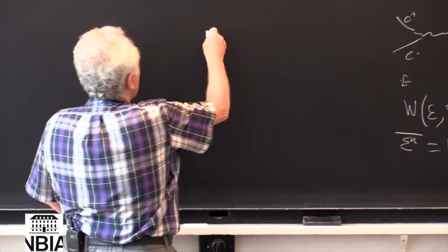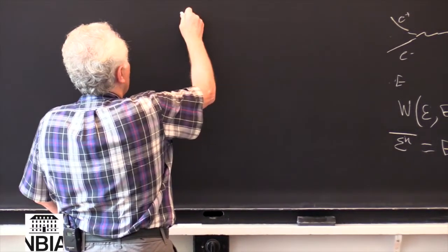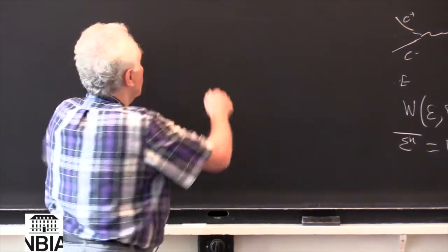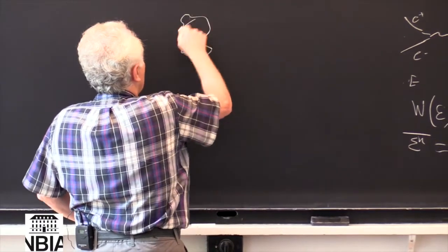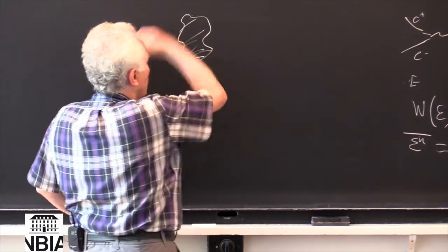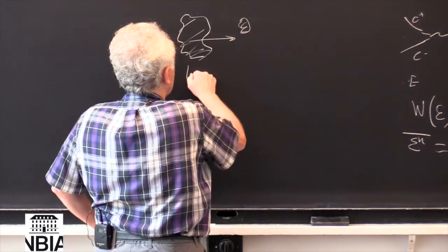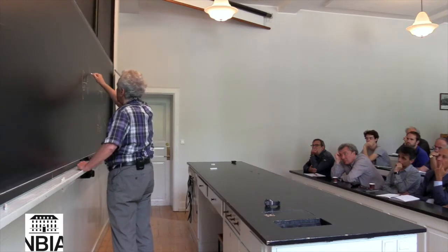The inertial interval is this: we have some source of energy which excites turbulence and generates some large fluctuations, which have the size L. Then we have the decay, the cascading process.